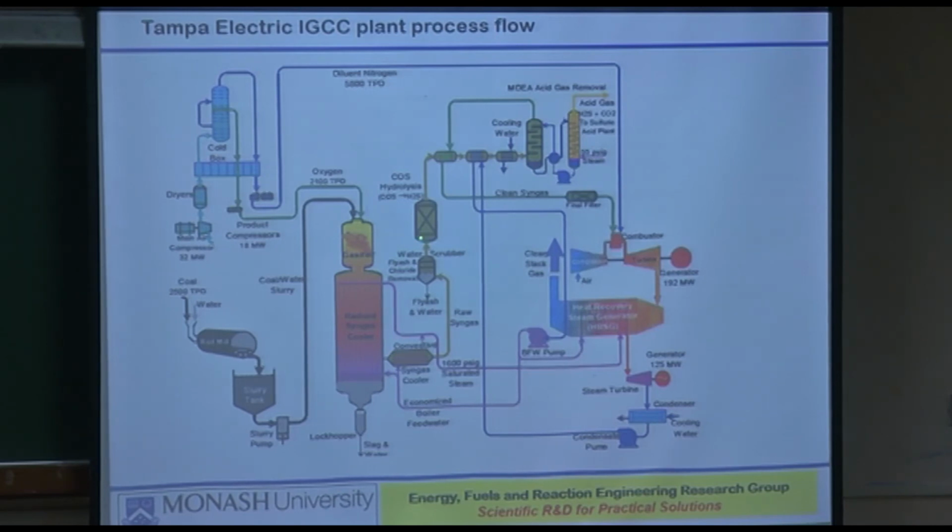No, H2S is removed. No, it's H2S, it is taken completely from there. That's not what I talked about. Here they have one particular filter which has taken out the sulfur. And here there is a scrubber system which does take out some of the sulfur gases, some of the chloride gases. But the final filter before going to the combustion takes out any residual particles that go to the gas turbine. So the gas turbine is protected all the time, so let's not worry about it.